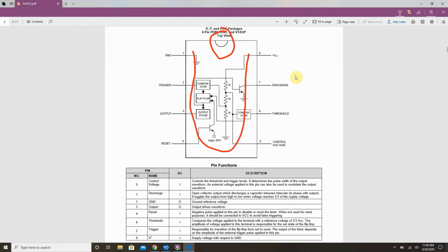And also you learned that it has to go in the proper way. Some of you reversed this when you put it in, which meant pin 5 was here and pin 1 was here, which was backwards. And obviously it didn't work. But these pins obviously are very important. This is what the inputs and the outputs all come from.